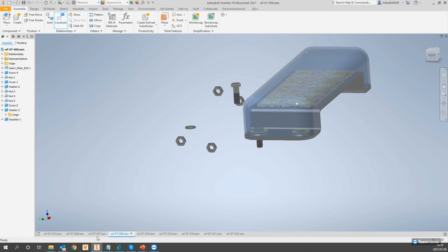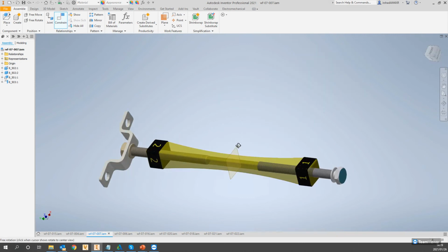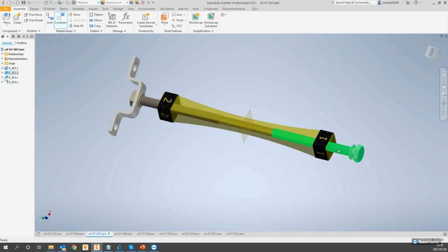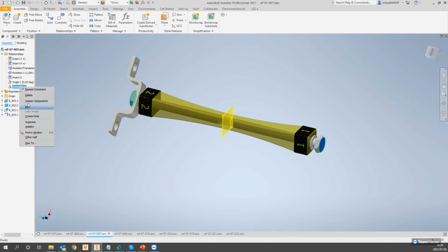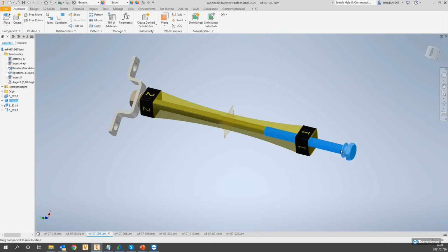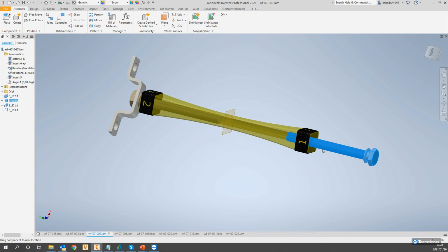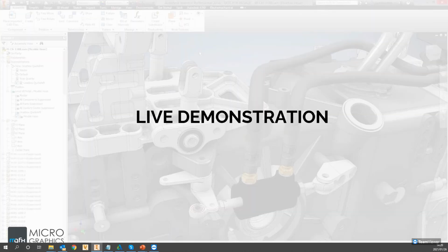Okay. Lastly, you'll notice that you have the symmetry. And I think I have a design here to illustrate that. Here we go. So you can see in this design, I've got some constraints. Let me delete the one that I've already done just to show you how it was working. So you'll see here that as I pull this out, I actually want the other one to pull out in the same direction away from this reference point here. So currently, as I'm doing it, it's just moving this screw on the number 1 side. I want number 2 side to also move in the same direction.